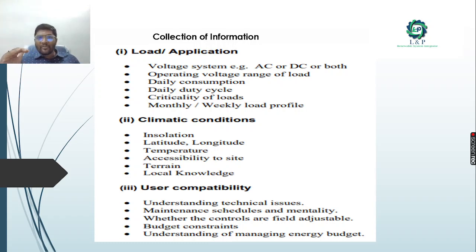Because when you plan for an on-grid system, if they are utilizing the entire solar energy in the morning hours, doing works continuously in the morning hours, then it is better to suggest the on-grid system. But if they need power only during the sleeping hours and a few morning hours, then it is better to suggest the off-grid system along with solar. In certain places some people may say, I need energy storage also, I am ready to invest in the hybrid. Then for such people you can provide these details.